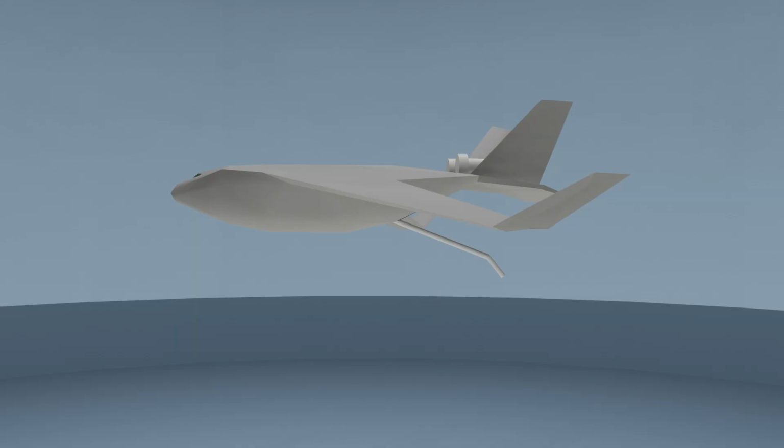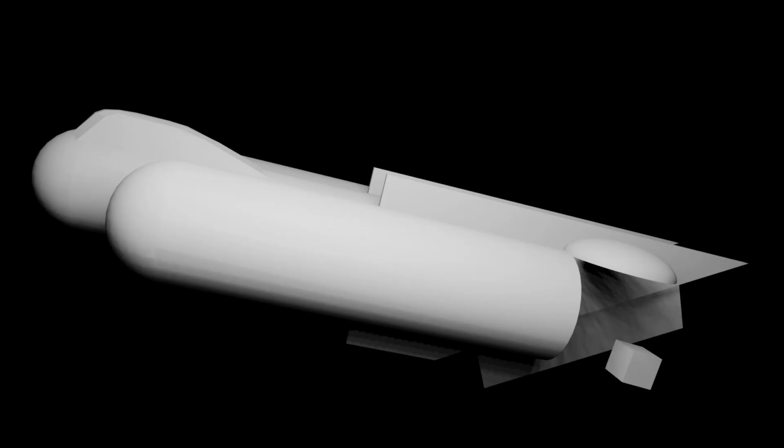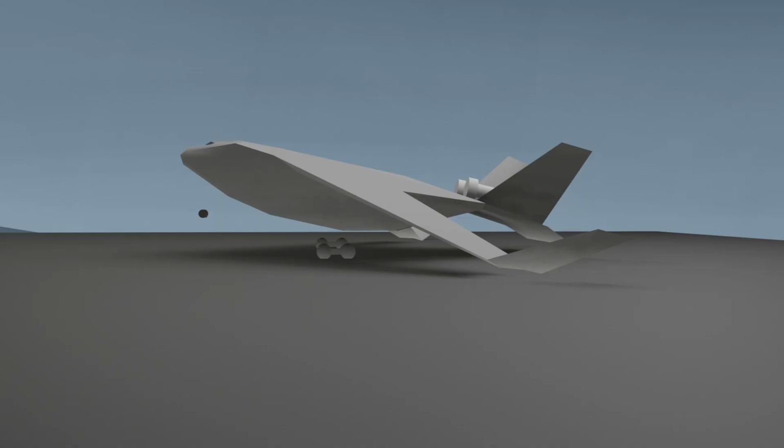For a military aircraft, a refueling boom could also be fitted, and it could be used as an air tanker. Additionally, as another military function, the tubes could be opened in flight, and the aircraft could be used to do airdrops. You could also drop things like bombs and cruise missiles at the back of the aircraft if you fit a suitable ejection system or delivery system to move the bombs and the cruise missiles out the back of the aircraft. The lower wing loading also means the aircraft could take off and land on shorter runways.